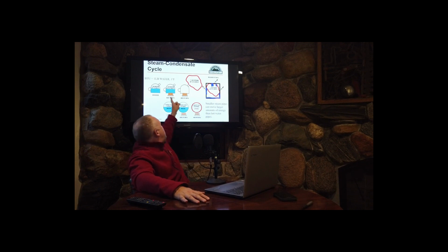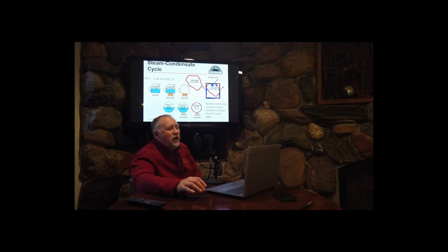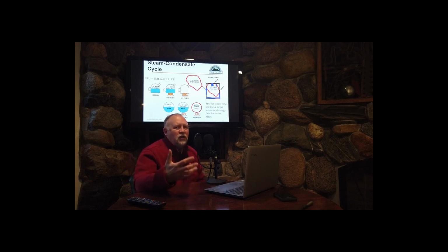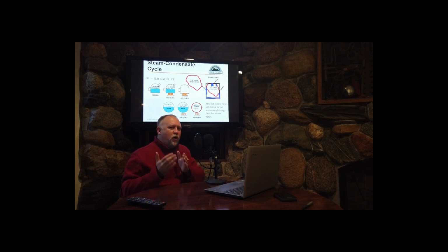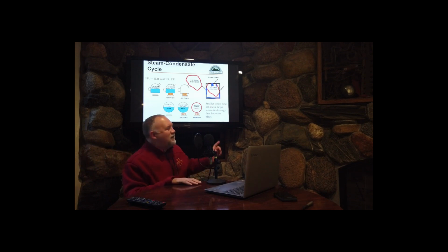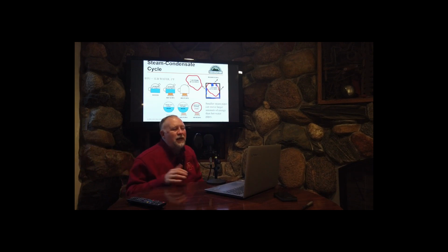All right. To take it from 212 degree water to 212 degree steam, we have to add an additional 970 BTUs. Per pound of water, that is a lot more energy that we're putting into the water, which means when we use it in a radiator or in a coil or at a building, and it condenses back, we get that same 970 BTUs out.